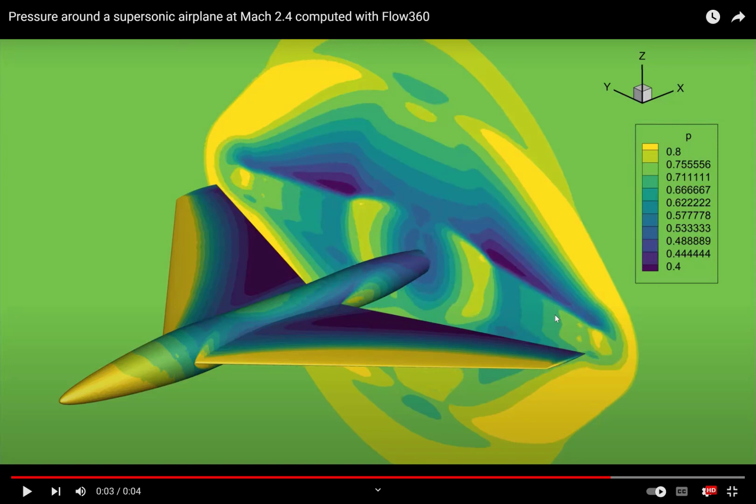That's how you see this triangular shape, because the wave propagates at a slower speed than the leading edge of the wing coming through this particular cross section. Yeah, question? Does the wave propagate out at the speed of sound? Yes, the waves propagate out at a speed very close to the speed of sound. You can actually calculate that for a very weak shock wave. Let me do this calculation over here.